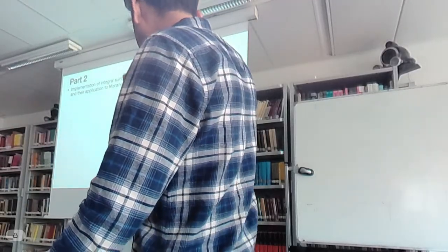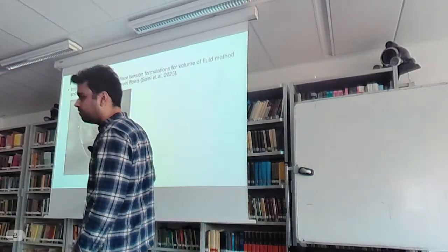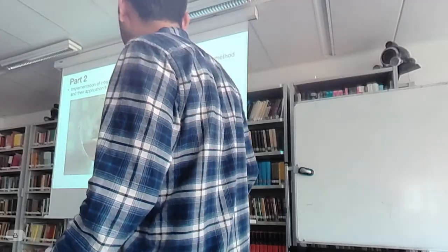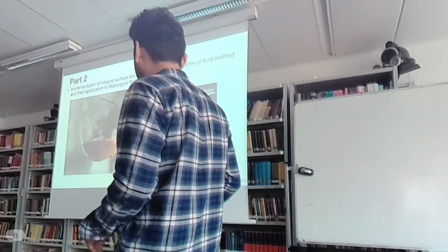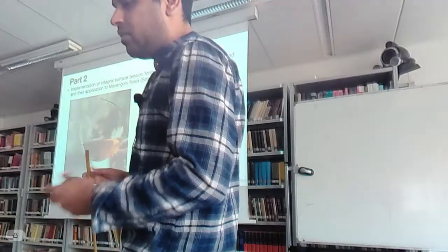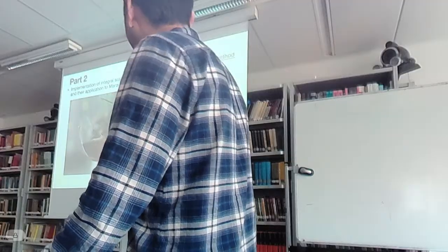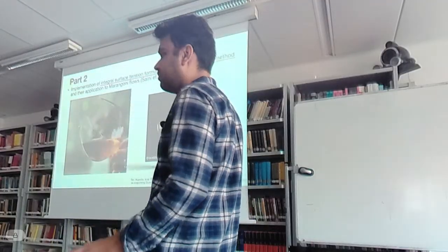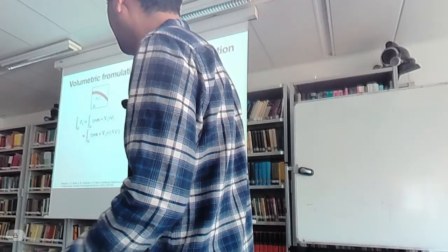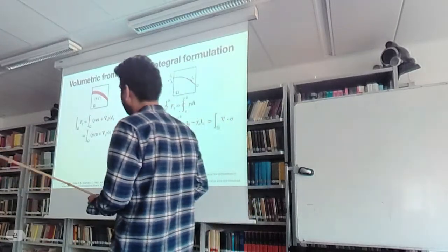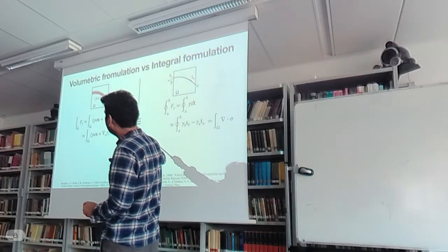For some other applications, you have these tears of wine that appear because of Marangoni flows, or you have evaporation of droplets, multi-component droplets, where you can generate evaporation driven or even solutal concentration driven Marangoni flows. The key idea is to implement integral surface tension formulation in volume of fluid, which is the new thing about this. So we have a classical volumetric formulation where the surface tension is added as a singular force with a delta function.